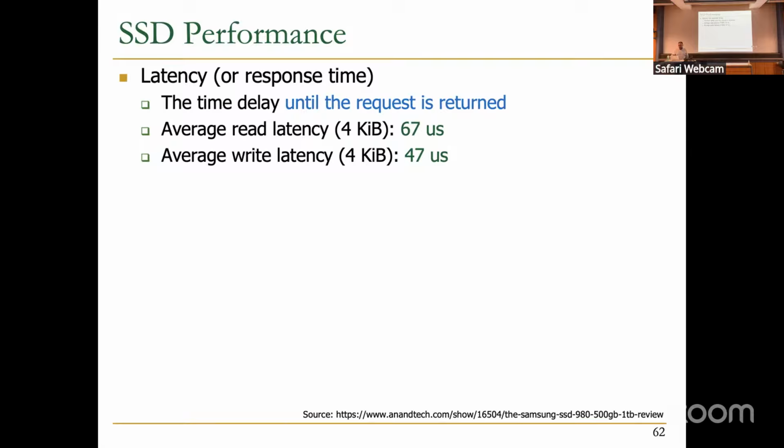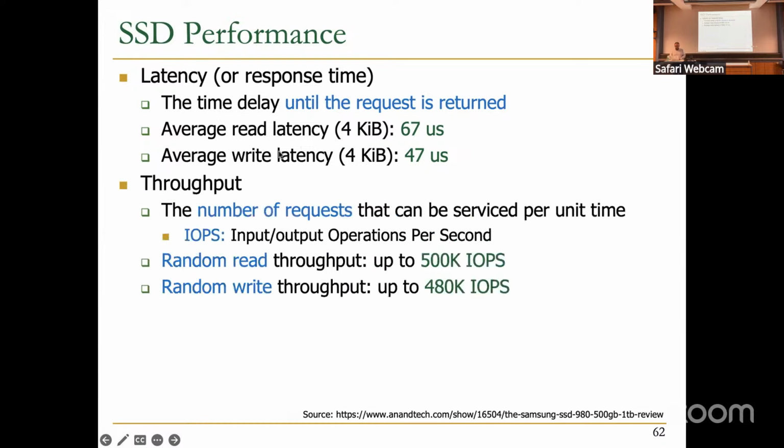So latency, or response time, is the time delay until the request is returned. We have average read latency, which is reported in some sources as around 67 microseconds, and average write latency is actually 47 microseconds. So you can see that write latency is lower even compared to read, because most of the time you write only in the buffer, the write buffer.